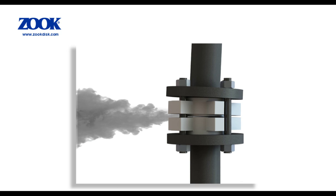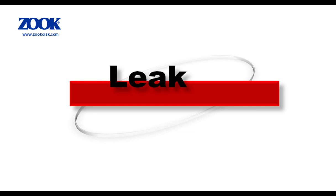Misaligning holder and disc components or incorrect torque patterns can also cause leaks. Similar to any tightening process, it's important to gradually increase the torque around the flange in order to provide equal loading to the assembly. Misaligned piping like that shown in this picture or incorrect flange torque can result in multiple leak locations across a rupture disc assembly. Some manufacturers offer pre-torque holders which allow the installer to preload the disc and create a leak-tight assembly prior to field installation.